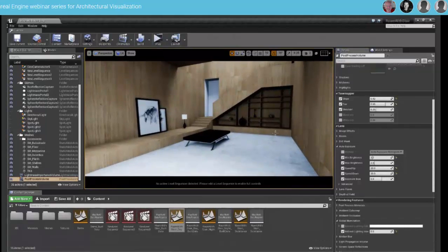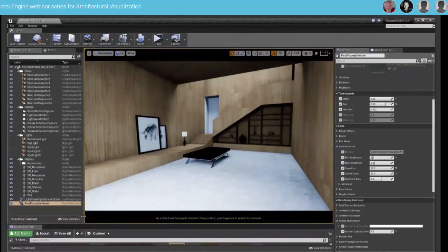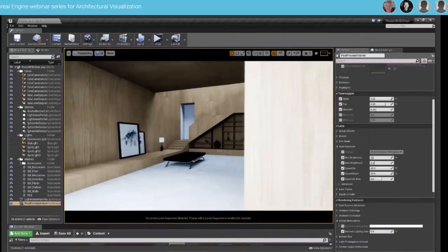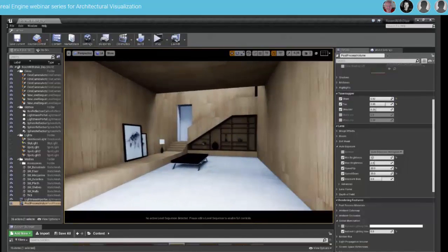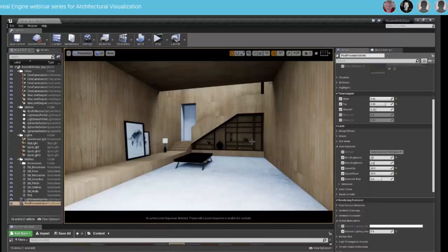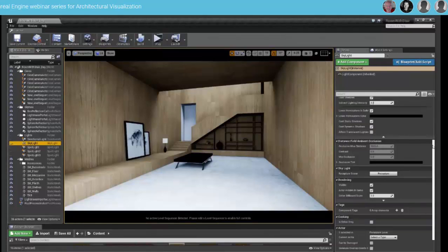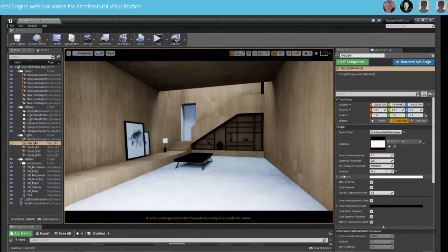Okay, so here, I'll make this a little bit bigger. Here we've got the scene with the skylight illumination only. This is the result of having this white cube map. Here I've set my intensity to 14, which is quite high but normal for an interior shot. The image that you see here is effectively the direct light coming from the skylight, and you see that we've got our nice soft lighting happening here.